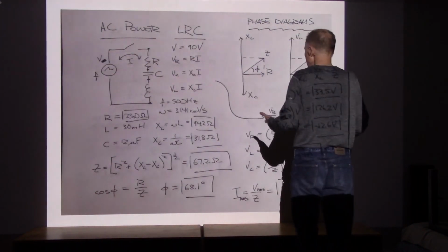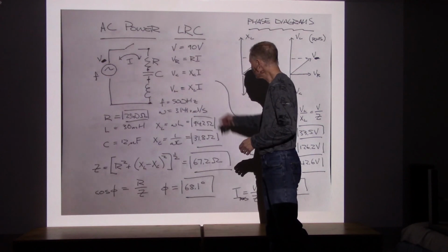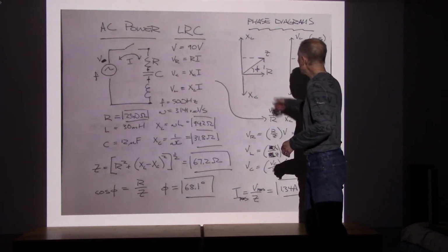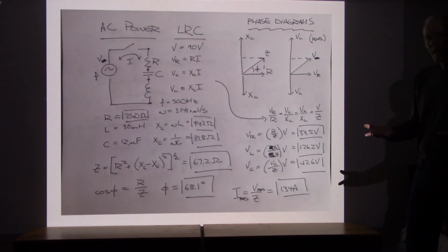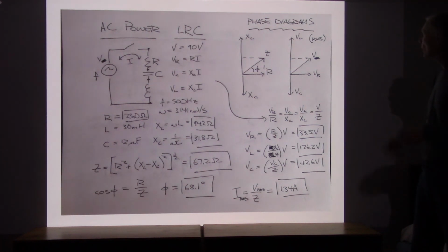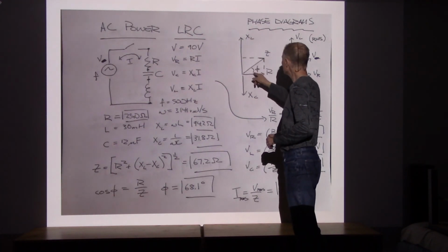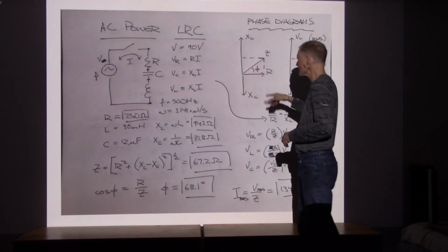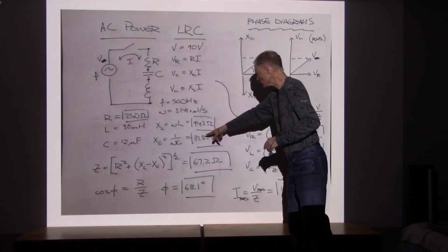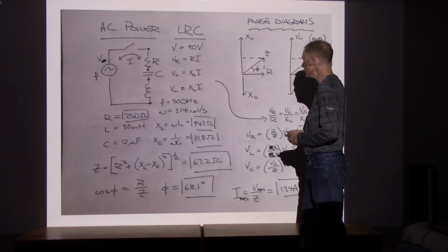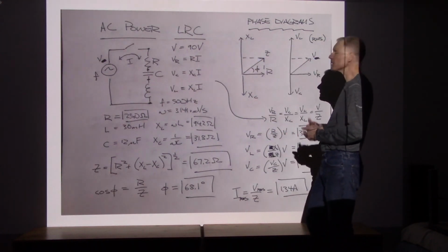Now, I don't always do this carefully, but if you do this carefully, it probably helps. What I'm doing is taking those three numbers, 25, 94, 32, and drawing my impedance diagram to try and match that. I didn't do very well. If this is 94, that should be like 4 times as big as this. This resistance needs to be smaller. Sorry about that. The capacitive reactance needs to be about 1/3. Again, not the best, but it's okay.